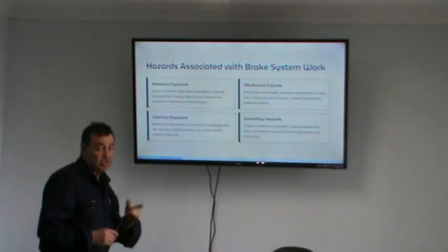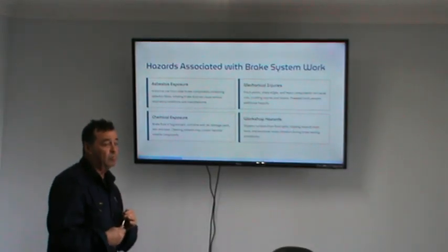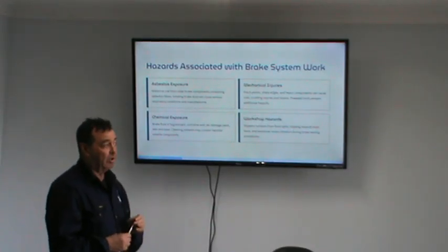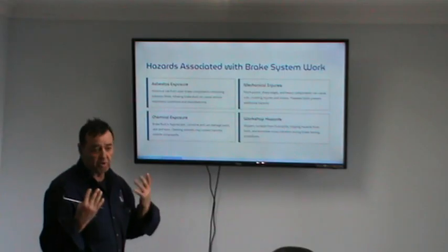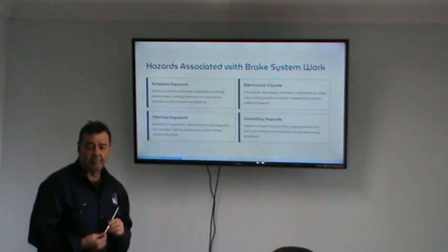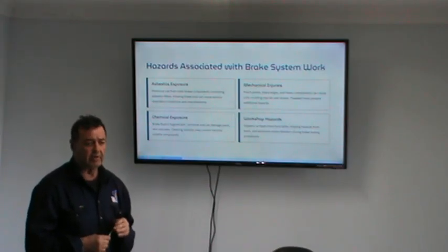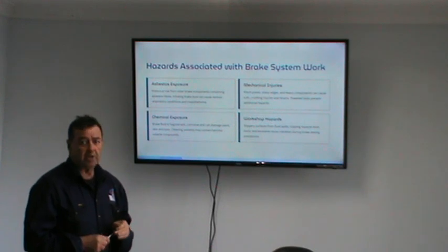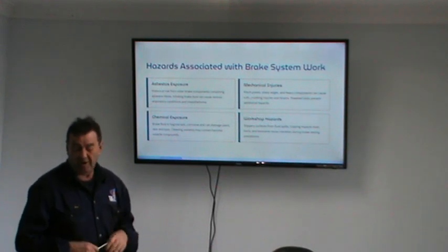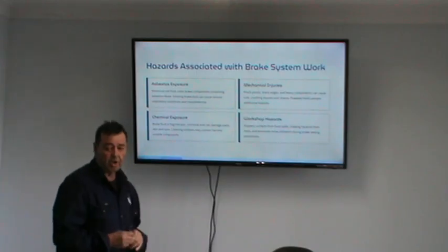Obviously, cleaning solvents like brake clean also are hazardous, they're highly flammable. They can knock you out, I suppose, if you sniff it. So always wear a mask, never spray it at anyone, in anyone's direction. Definitely don't light it on fire, because it's quite volatile and harmful.